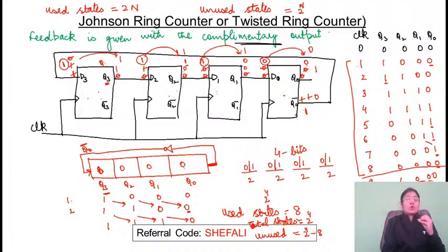बच्चे, आपके पास synchronous counter है, asynchronous counter है, Johnson ring counter है, basic ring counter है. Anything is there. If n flip-flops are there, maximum states, maximum combinations कितने हो सकते हैं? That is 2 raised to power n. These are the total possible combinations. But used are here, how many combinations are used? That is just 2 into n. So this represents the number of unused states.